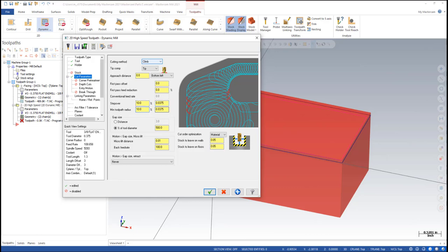For minimum toolpath radius, it's not going to affect what we're working with here, but in certain situations, like if it was trying to machine a pocket kind of like this, you can see it highlights these little loops because it'll make a pass and then it'll cut back, and every time it enters and exits the cut, it has to loop in these little radiuses, and you're telling it what the minimum acceptable size is. So if you're trying to get features that are like here, it gets pretty tight. And if you have too big of a radius defined, it's not going to be able to drive the tool in without violating that radius, so it'll stop. And so it may machine it like up to here, and then it would just quit.